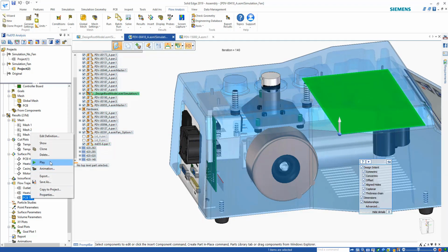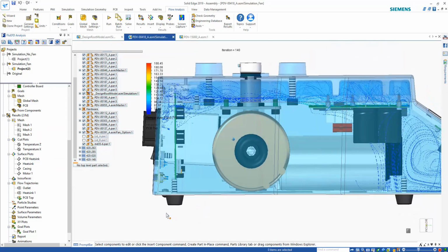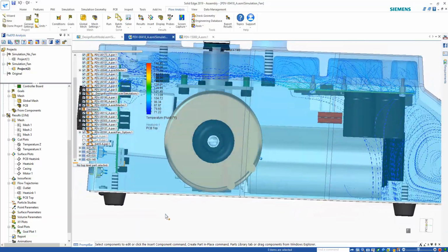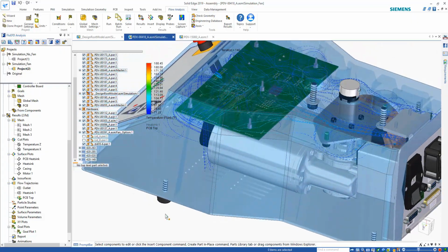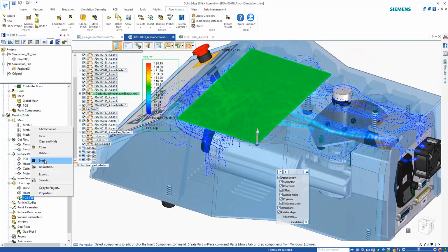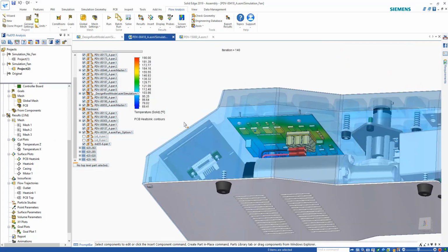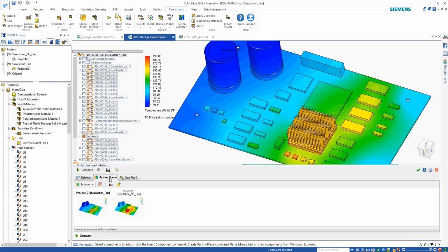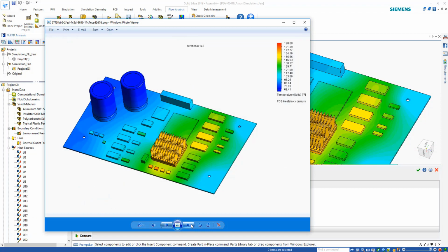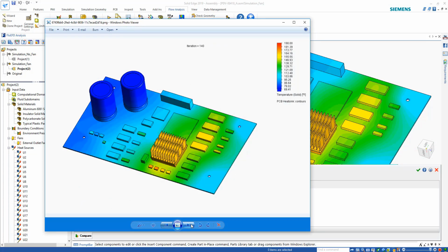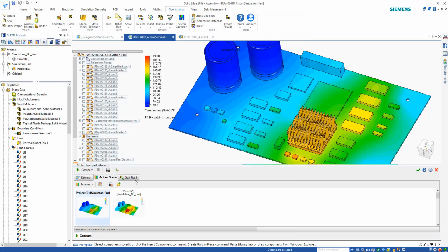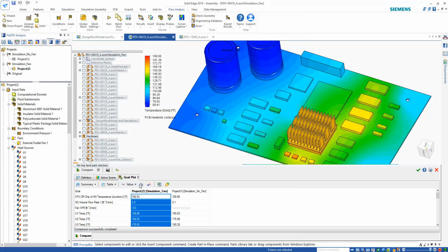The flow from the top face of the PCB shows a similar flow profile. Temperatures on the board have been reduced significantly compared to before. Comparing the results shows a noticeable difference in the colors. Numerically comparing the results shows that adding a fan reduced the CPU temperature by 23 degrees Fahrenheit. All the other components see a significant drop between 17 and 28 degrees F.